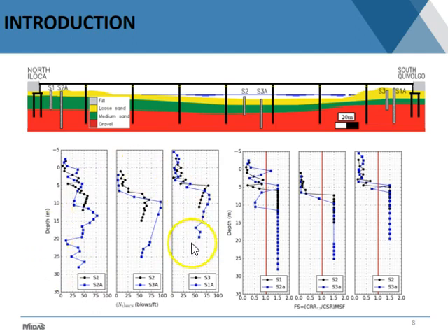Now, if you take a look here at the bottom left, you see the SPT profiles versus depth for each one of those borings, S1 and S2A together. They pretty much look similar here in the upper part. If you take a look at the scale, you have 25 blows per foot, and then 50 and 75.